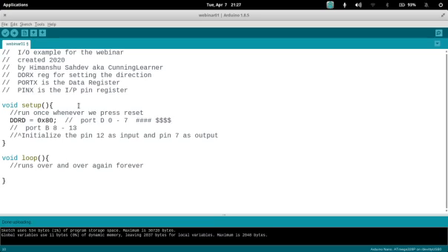It starts from 0 to 7 on port D. So let's go ahead: 0 1 2 3 4 5 6 7. So the 7th bit. For hexadecimal, 1 2 4 8, I want to write 8 and 0. So I have written 0x80 already. We can also use shifting operators, like 1 left shifted by 1 2 3 4 5 6 and 7.